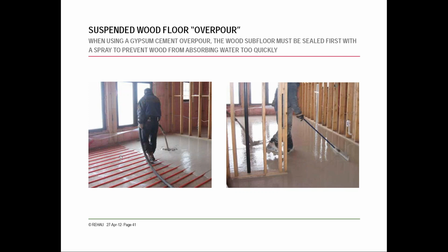All right, so here, this is after they've got everything set. The concrete guy is in here and laying down his overpour. Quick note here at the top, you want to make sure that if you're not putting anything over the subfloor, the concrete guy is spraying it with a sealer first, so that when they're pouring this, the wood's not absorbing the water too quickly and pulling it out of the concrete.